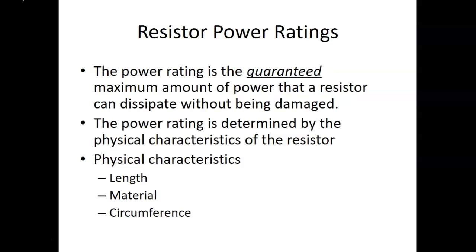Okay? So something like a space heater, or like I said, they make resistors as big as me to go with industrial sized overhead cranes. They make resistors even bigger than that. The reason they are so physically big is because the current that they must draw through them is a truly massive current to just get these cranes started. Okay? And if you don't have a good enough sized resistor on that, what do you think happens? You're liable to blow up your resistor.